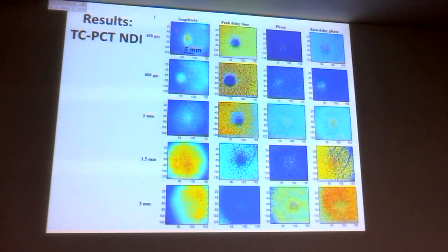I see the amplitude now. So the amplitudes, unfortunately, also depend on the optical properties of the surface because there's a reflectivity there. So the reflectivity of the surface, especially in a metal, matters. Whatever stuff is on the surface, that's going to show up. The phase is better because it does not depend on the reflectivity. The phase is a ratio of two signals, quadrature divided by in phase. So as a result, the reflectivity cancels out. So that gives you a true thermal wave image.